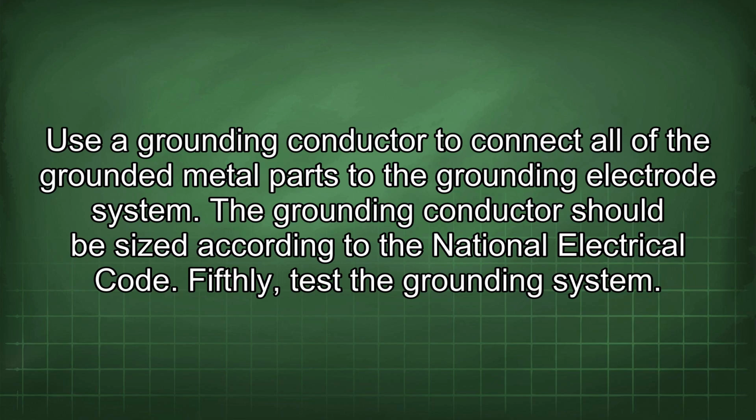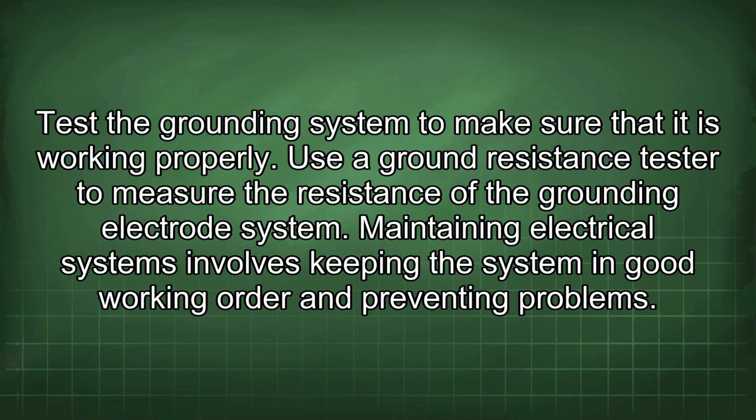Fifthly, test the grounding system. Test the grounding system to make sure that it is working properly. Use a ground resistance tester to measure the resistance of the grounding electrode system.